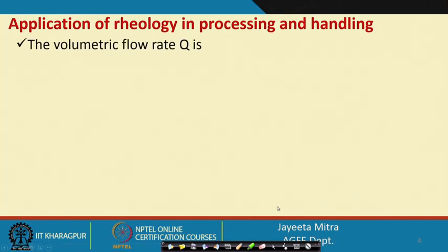Next is, if you want to analyze the volumetric flow rate. So, volumetric flow rate, what we can do simply, we can integrate from r equal to 0, the center, to r0, 2 pi r dr into Vz. Okay. Vz is the velocity, which is a function of r, and here we can write d of r square.